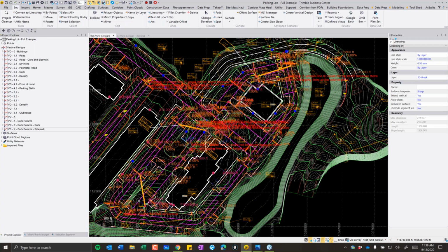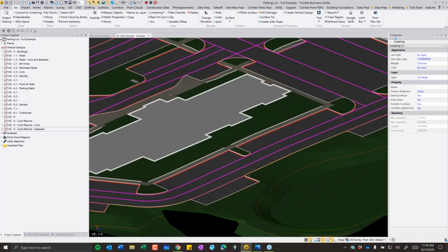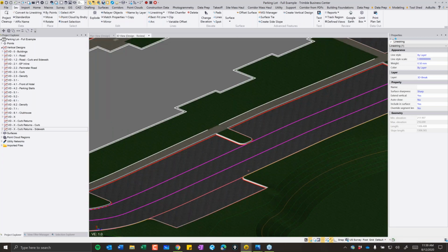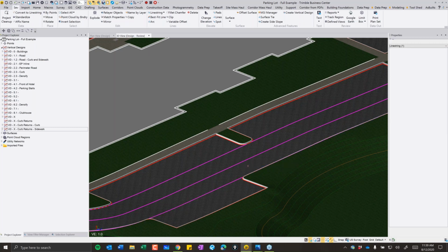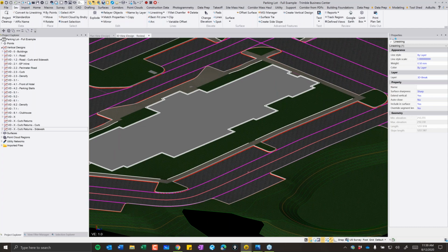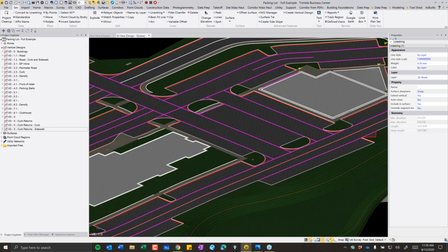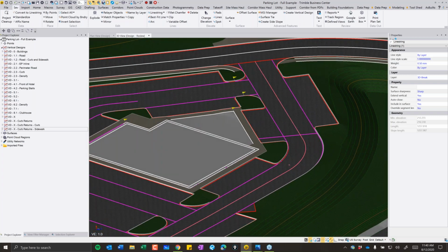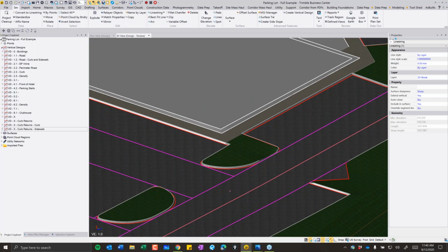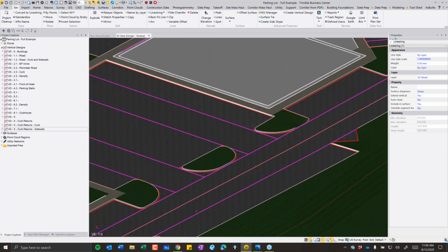At first, I didn't add that to my 2D line work, but now I do. These purple or magenta lines are my break lines. I treat these lines like how we would grade it or how we're going to pave it. So I add those in there and I supply those to the field. I may not supply those to the machine control, but I supply those to the data collectors, because ultimately that's what's giving the model its structure, its rigidity. So to me, those are crucial to have, because that's going to reinforce to the field, okay, these are the lines we need to snap onto to really shape this model and to make it happen.